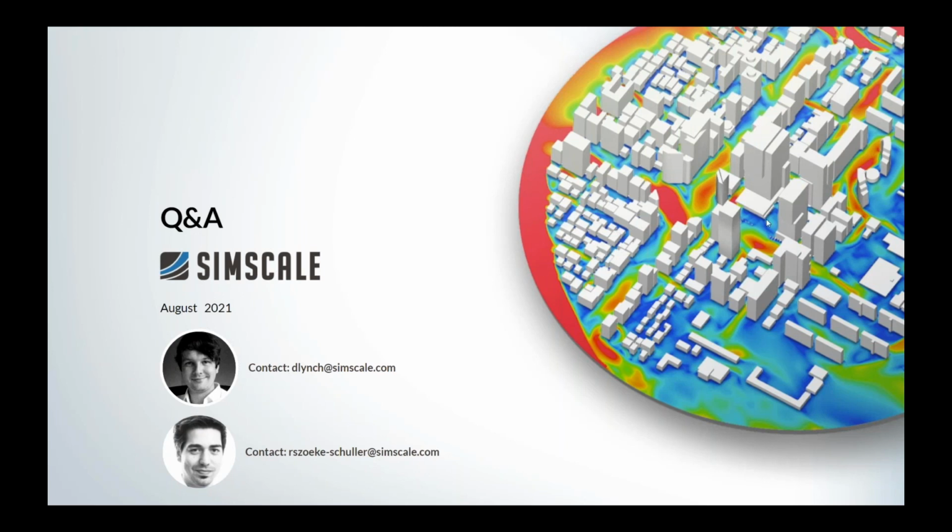And also we've got a question, what type of file is required for the building geometries? Can I use Rhino files, etc.? Maybe just to hit that on the head. The most common file format for pedestrian wind comfort tends to be from Rhino or Revit, in which case we prefer to export these as STLs and upload them to the platform.